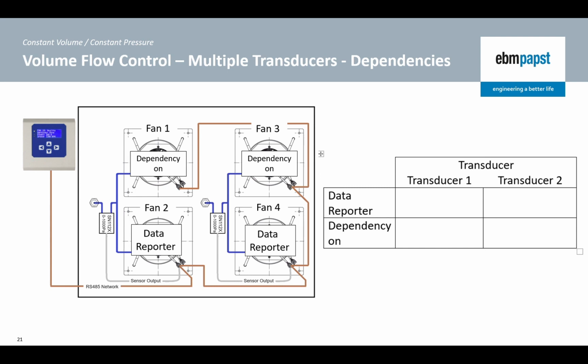In this configuration, the MDC firstly detects the number of sensors fitted to the fan array. If there are fewer sensors than there are fans, the MDC will determine which fans are connected to which sensor by running each of the remaining fans in the array individually. Once this installation routine is complete, the MDC will know which fans have a sensor installed and which fans are additionally contributing to the averaging pressure circuits in the fan array.